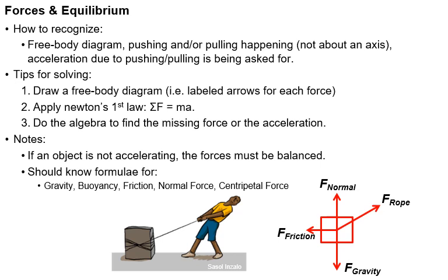So for force problems, what are the tips? You often should draw a free body diagram. If you're going to have a lot of forces involved in a situation, even more than one, draw the free body diagram. Apply Newton's second law, so the sum of the forces is equal to the mass times acceleration. Note that you have to break this into components. This is really the sum of the horizontal components of force is equal to the mass times the horizontal acceleration. And it's really the sum of the vertical components of the force is equal to the mass times the vertical acceleration.